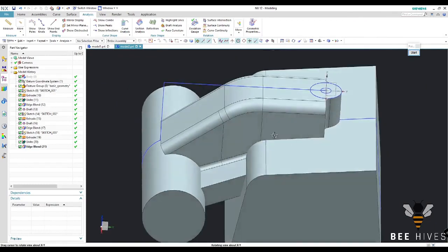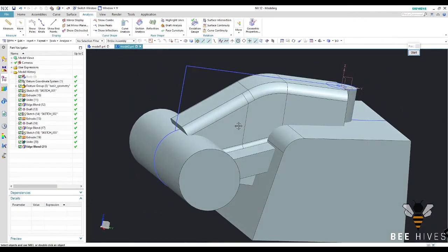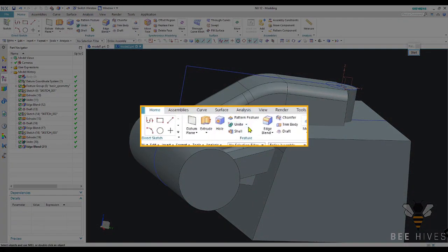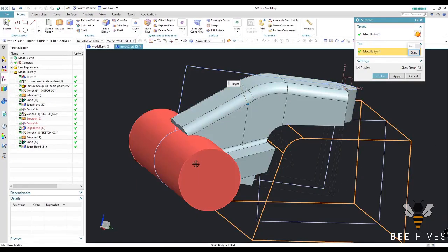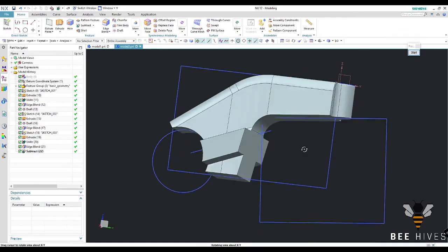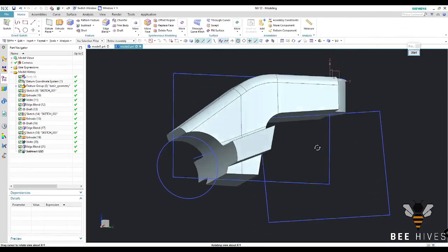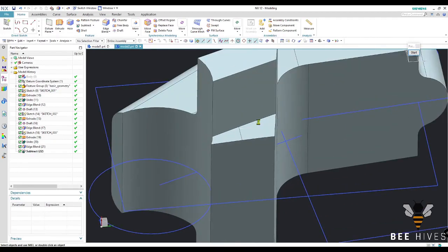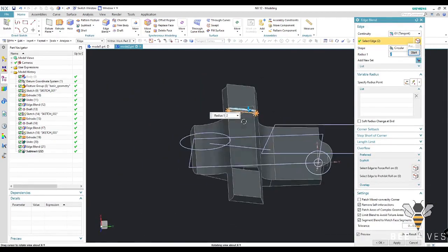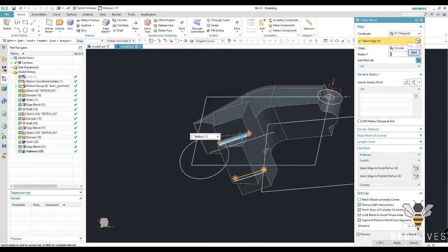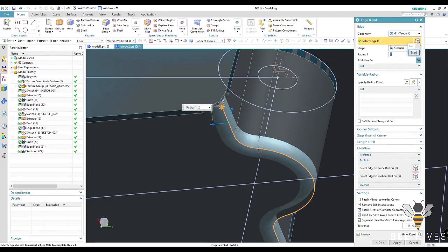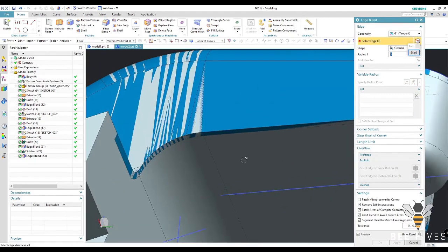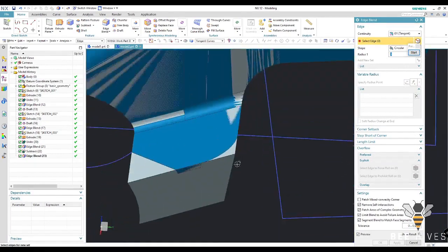Say okay. Now simply subtract the component. Use the subtract command from this body. I'll remove this and say okay. Now you have a complete solid entity here. You can go ahead with the blends so that shell becomes easy to operate, or even you can go first with the blends what we need. 3, yep. So this is the 3 where we need the dimensions or blends.